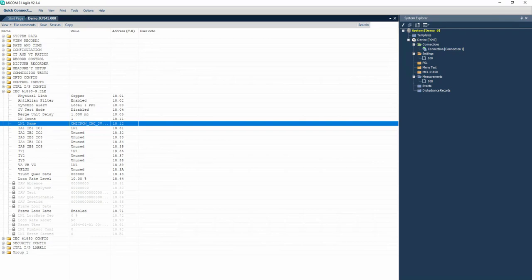For my demonstration, I don't use the other windings, just simple overcurrent protection. But in the coming videos, we'll demonstrate differential protection for 2 windings transformer and 3 windings transformer. In that case, we have to have those logical nodes defined for those currents. This is for the neutral current and also for the voltages. Also, I use the logical node 1. That's it for the configuration here.